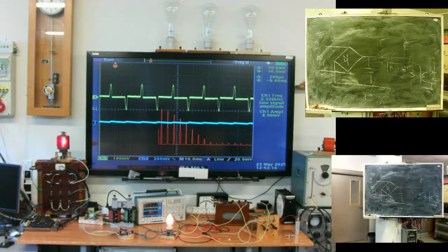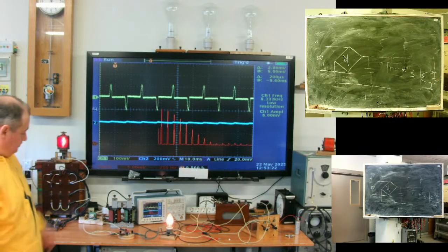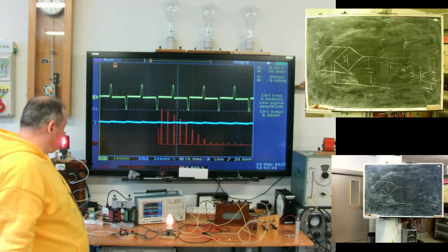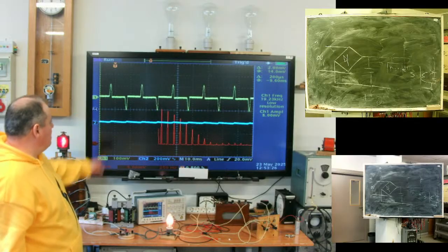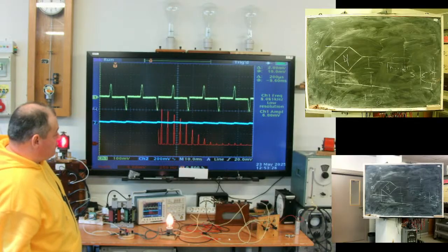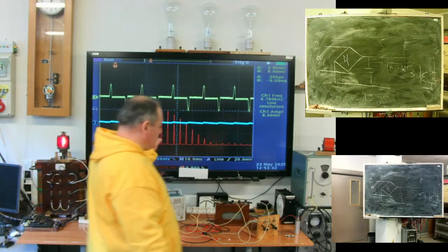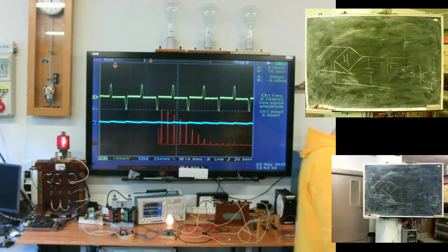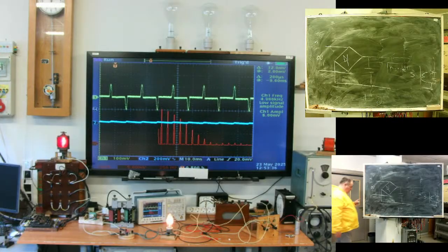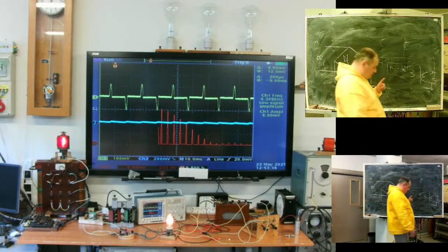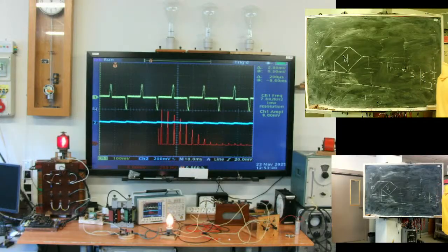Now deeper. Rectifier current contains third, fifth, seventh, and so on harmonics, and is in the form of short pulses. But this part is simple. At this part we see single phase.